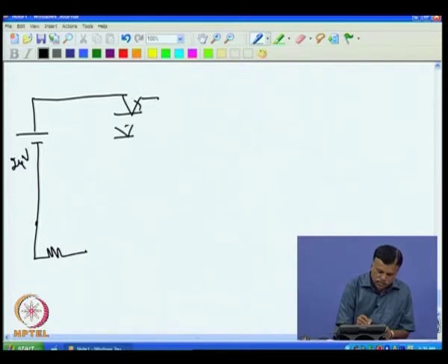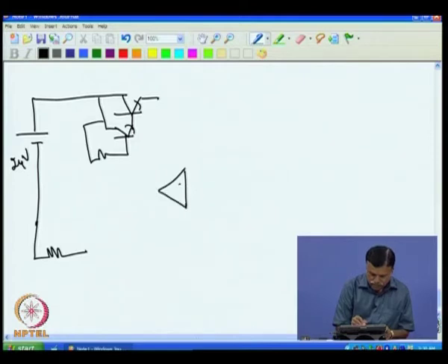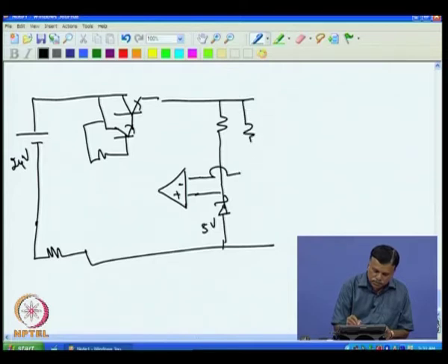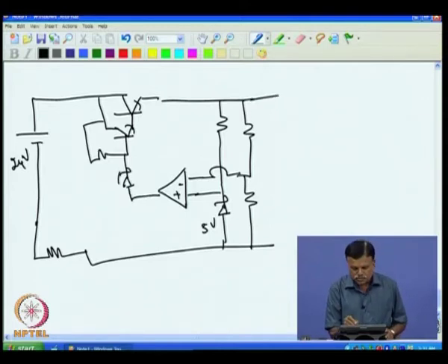That is done like this, then this resistance is used, then we have a voltage regulator, so this gives you 5 volt. Then the output is sensed partly, then we use the zener to boost the voltage, which I already discussed. Then we put one small capacitor to avoid the oscillations, then we have our current transmitter connected here.